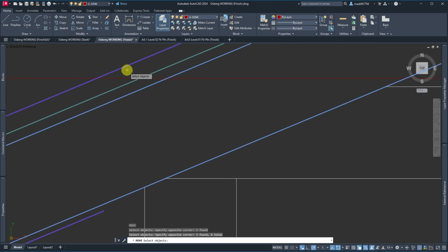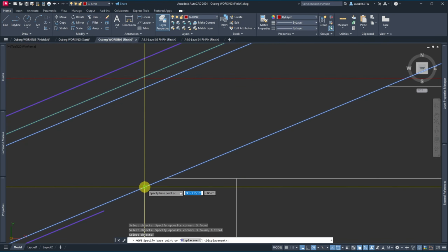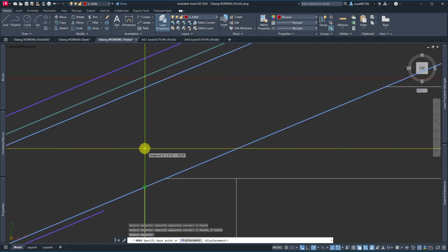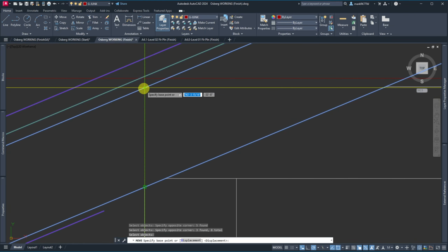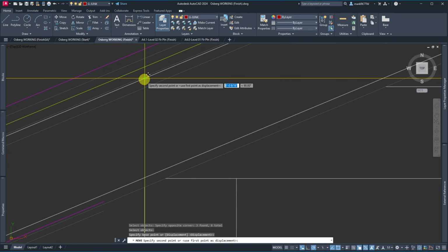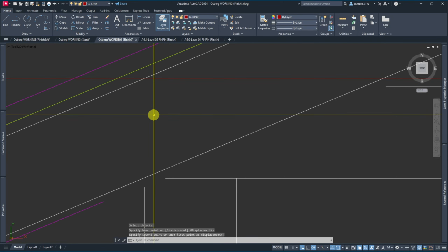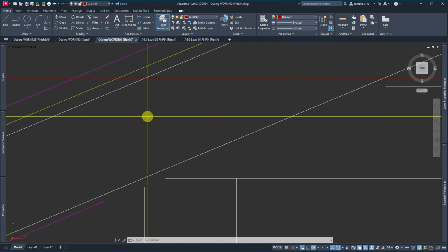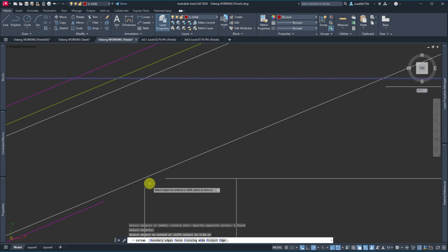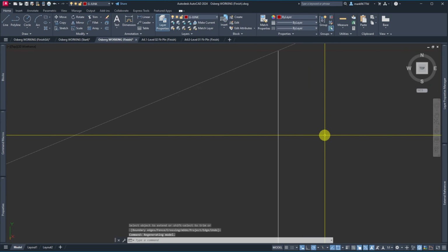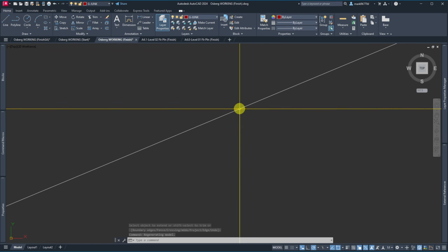and I'm going to zoom in because I need to do a projection, because I want to move straight above my baseline here to that top line of the top chord, and tell it that I want it to be at 18 inches of height. There. So with that in place, I should be able to extend this up, and it should make a perfect intersection. As you can see, it is awful darn perfect.